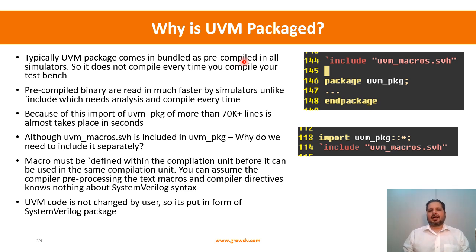And the second thing is, why do we have to tick include the UVM macros? Here, if I put a tick define within a particular package, that doesn't mean anything. Macros do not understand anything with respect to SystemVerilog, because as we have seen in the overall processing chain, it's a pre-processing step.